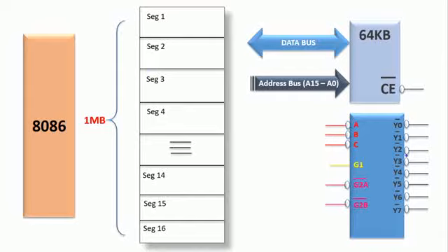Okay, so when you connect one of the output lines of the address decoder to the chip enable signal, this memory device will be mapped into one of these segments. To which segment it is mapped, we will see. As of now, I would like to map this one.